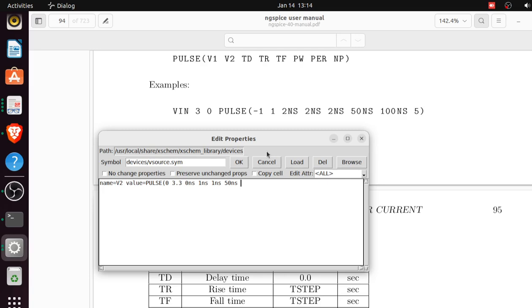For the downtime, I want to make it equal. So it takes 1 to rise, 1 to fall, then 50 to remain constant, so that's like 52. For the next 52 nanoseconds also, let it be reading 0. So at the end of the day, the period is 52 times 2. So is that looking like 104?